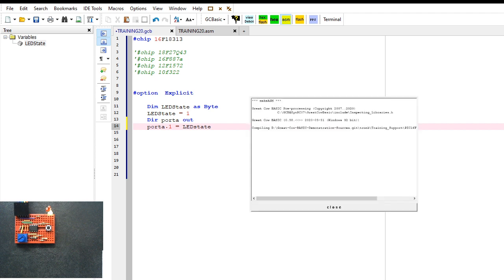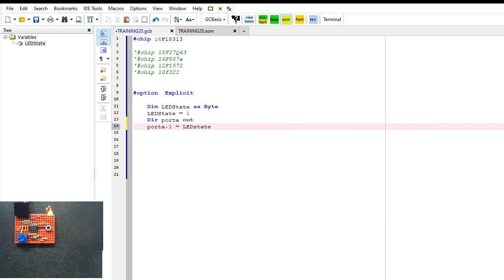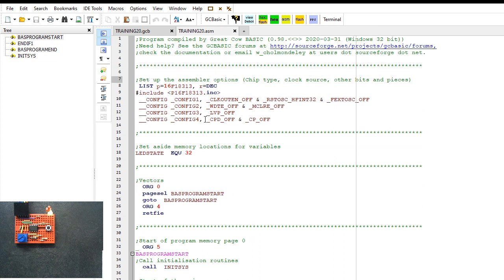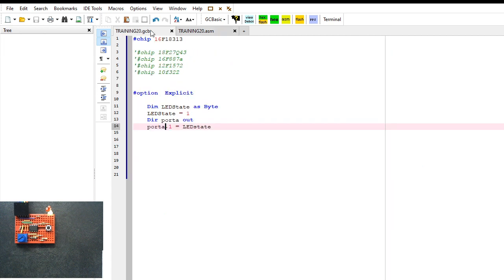There we go. I will put our code back. Now, what's interesting is it's generated this assembler file. We generate reports. We saw those yesterday, but I'm now going to show you how to generate those reports inside of a different assembler, a linker tool. And that linker tool happens to be part of MPLAB X. So if you go to your MPLAB installation, you select your version, you will find a folder called MPLAB X, MPASM X. Click on that,